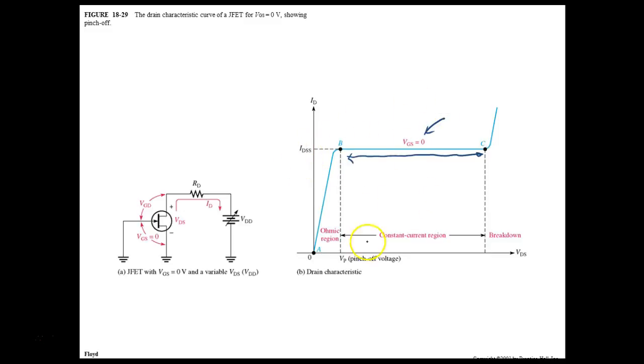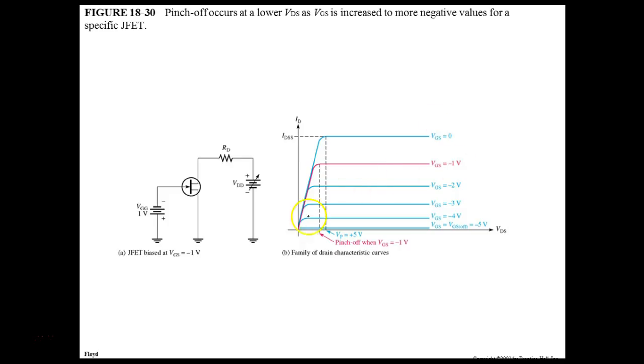Now this pinch-off current is referred to as IDSS. So we need to operate above pinch-off in the data sheets to allow the gate to have total control over the current. Now what we do is we come up here and we develop these, and this will show you what actually happens. So here this would be IDSS, right? You understand? And then this would be where we would operate. So IDSS is given at... we call this operating above pinch-off. Are we okay?